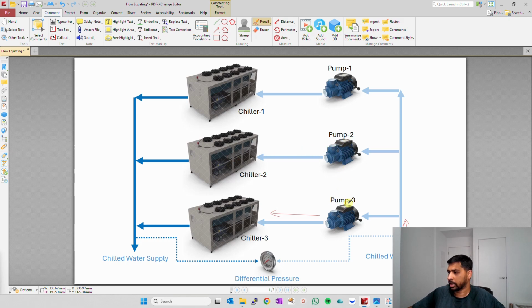And then if chiller 2 comes on, even though the pumps are rated the same, the suction pressure being here might get an additional flow, not on a very high margin, but maybe a little bit here and there with the tolerance. So let's say if this pump is rated to 1300 GPM, this might be getting 1300, while this is also rated for 1300. This might be at the same speed getting maybe 1250 due to the suction pressure coming first to this and then to this.